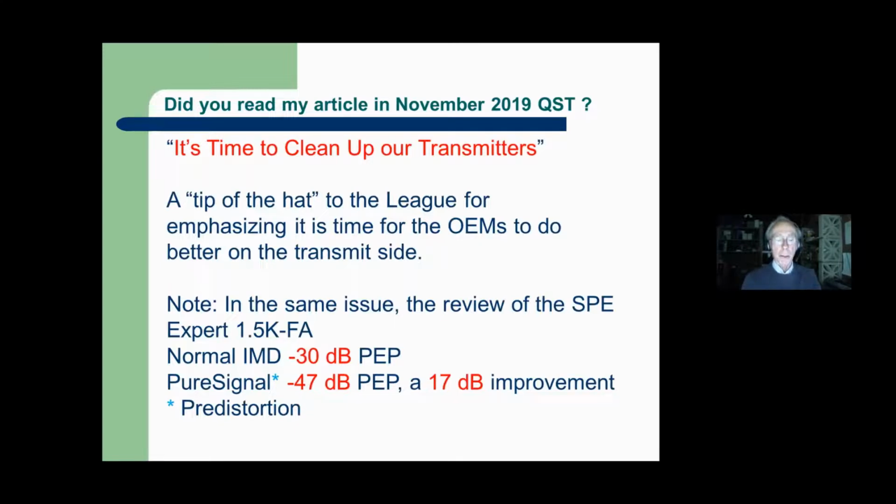It was interesting that in the same issue, they tested the Expert 1.5K FA amplifier. It was a typical LDMOS, minus 30 PEP. If we measured it with the spectrum analyzer, it'd be minus 24, but we'll just go with the PEP method. I call it the feel-good method, but that's what we have. But they did Pure Signal. It improved 17 dB for third order. So that's what I wish we all had. I don't own a rig that does it, but I wish I did have that kind of clean signal.